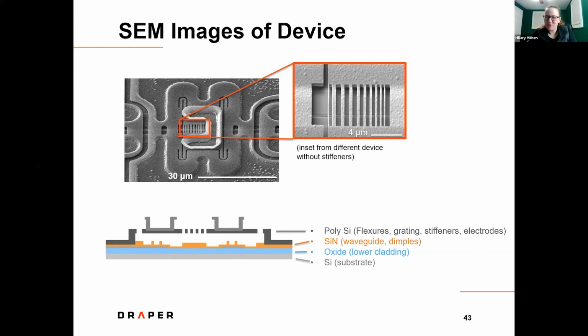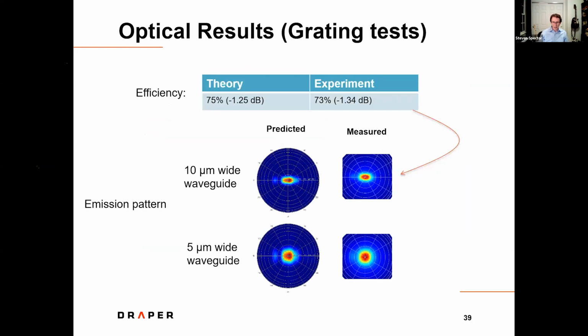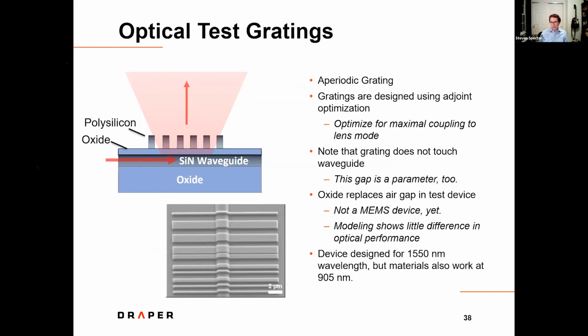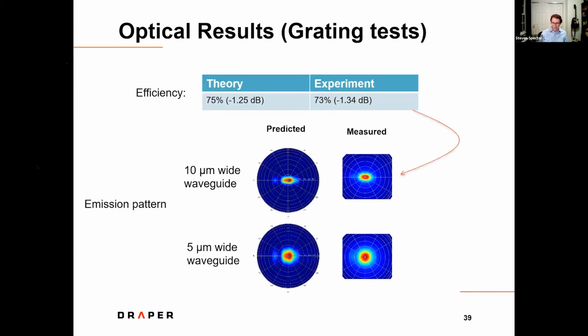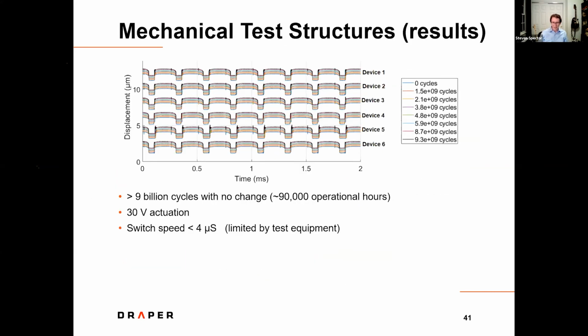A couple more questions for the lens assisted LiDAR. Is it possible to use a source array, VCSEL or LED, instead of an array of grating emitters? Yeah. In fact, I did mention in the beginning, it's sort of a different technology, so I didn't talk about it because it is so different. But you could just simply put a VCSEL array in your focal plane and turn the VCSELs on and off.